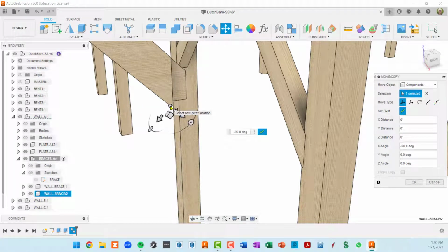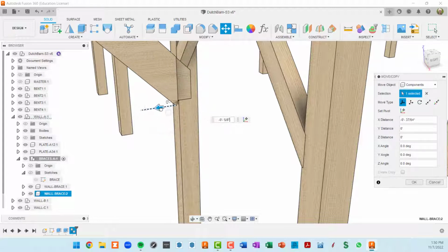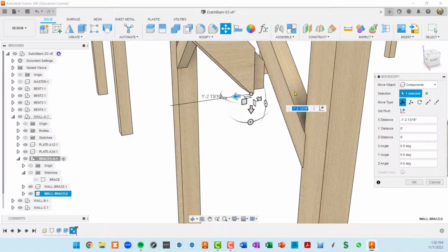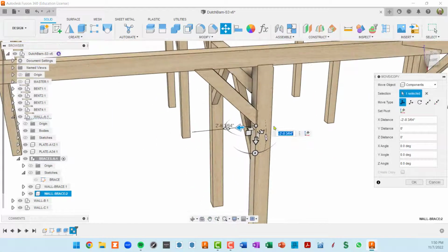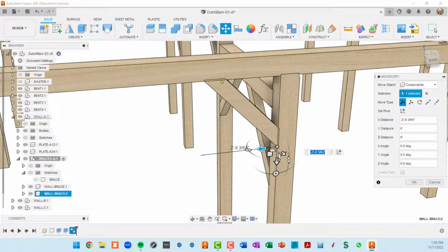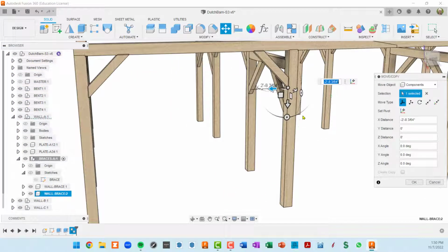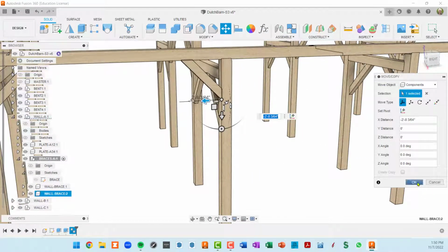So an easy way to deal with that is click on the point that you want and then use this rotation. And I should be able to rotate that a known number like, okay, 45 is going to give me what I want here. So I click on the green check mark and now I'm out of setting pivot and I can move horizontally and click on that surface, and there we are. We're a 1/2 inch in and also 1/2 inch here. So let's click on OK.